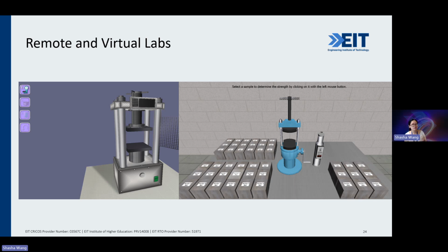So for example, to do the actual concrete test, we have to have the actual concrete sample, right? However, if we want to do some in situ testing on, for example, an existing structure, apparently one way is that you can try to core a specimen from the existing structure or infrastructure, and then you can bring it back to the lab and do the test.